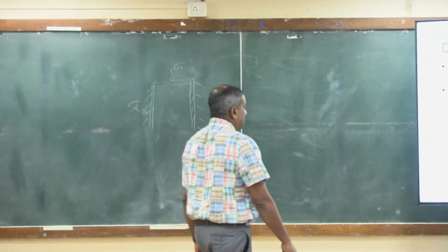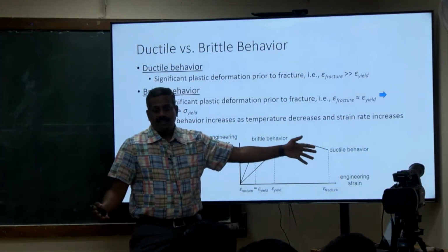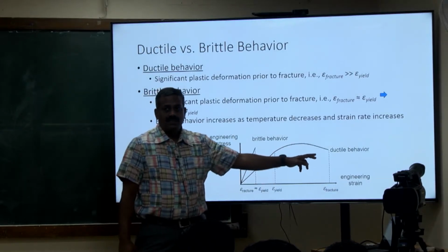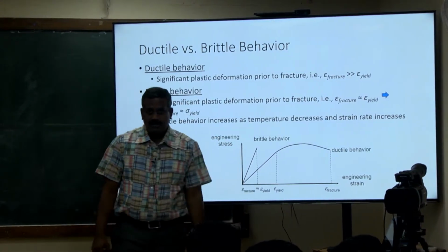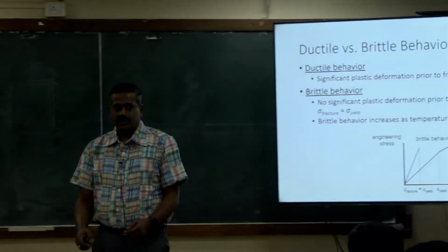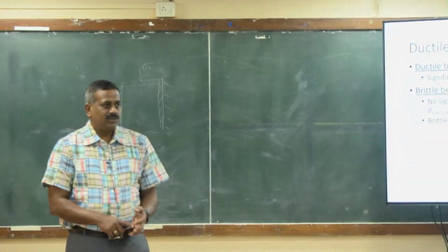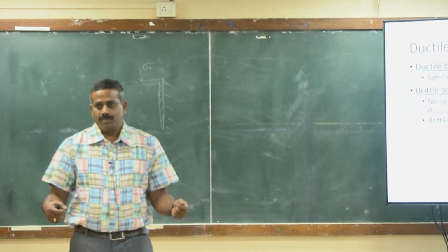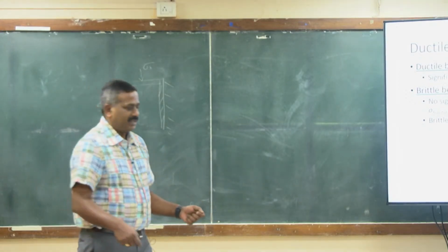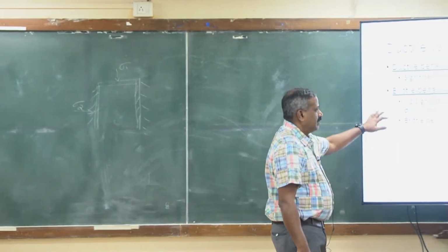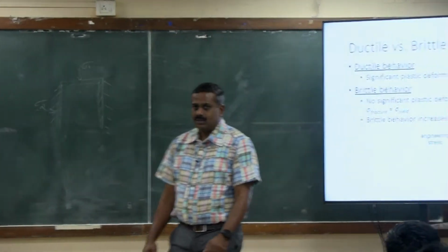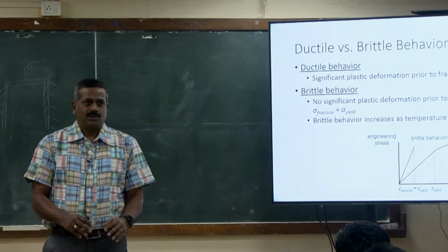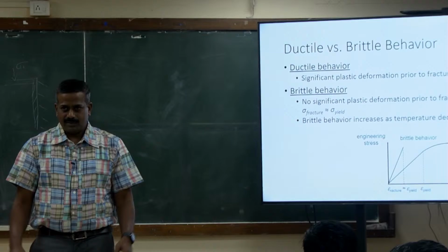So, ductile behavior, again, there will be significant plastic deformation, comparing to a plastic sheet, right? So when you're applying some tensile load, it keeps on pulling until it breaks, right? But if it's brittle, what happens? It breaks suddenly, right? Like comparing a plastic sheet to a piece of paper. When you pull a piece of paper, it suddenly breaks, right? So that's brittle behavior: the fracture strength and the yield point will be almost the same. When you cross that elastic limit, it breaks, okay?